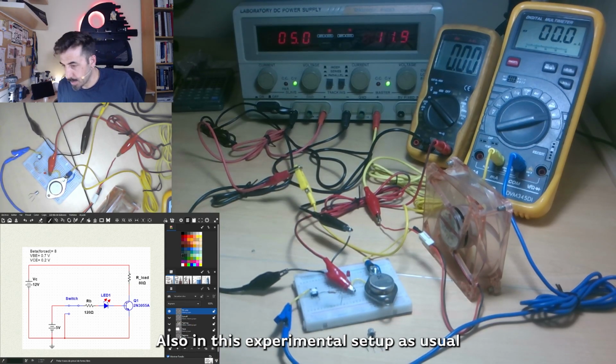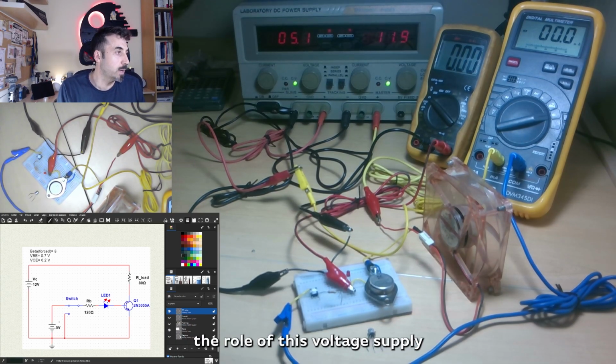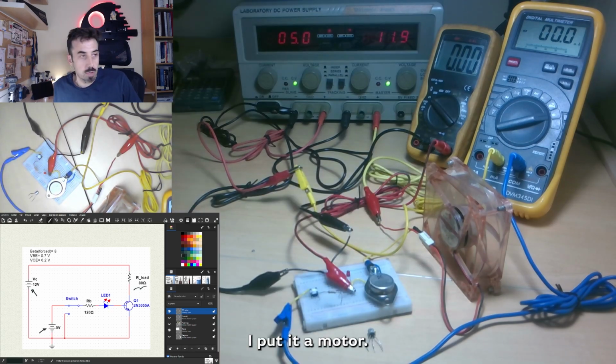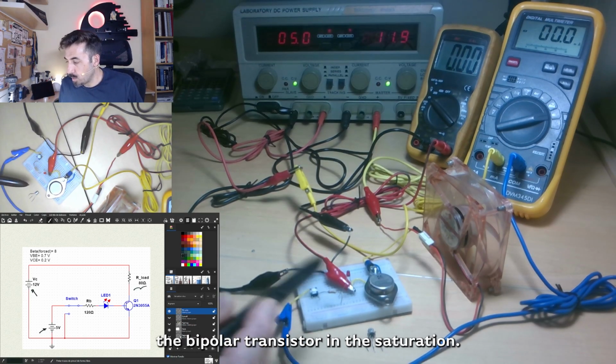Then underneath you have two more pins, the base and the emitter. Also in this experimental setup, as usual, you have the 5 volt that is going to play the role of this voltage supply, and also the 12 volt that is going to play the role of this other. The load is interesting because I put a motor. Motors, or anything that demands a lot of current, are the typical thing that you put in the collector when you make the bipolar transistor work in saturation.